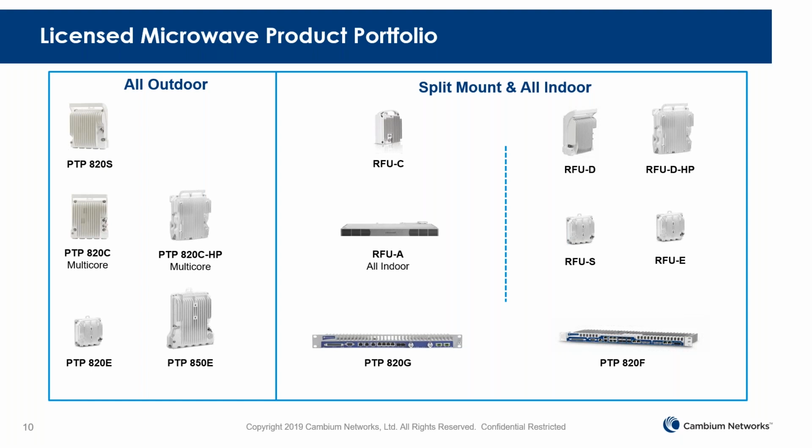But if you do have some certain channels you don't want the radio to jump into, then you can block those channels from the UI. You can see I only want the radio to scan from channel 10 and above. You don't want to go to lower frequency. Because there are certain things there, so you can do that.